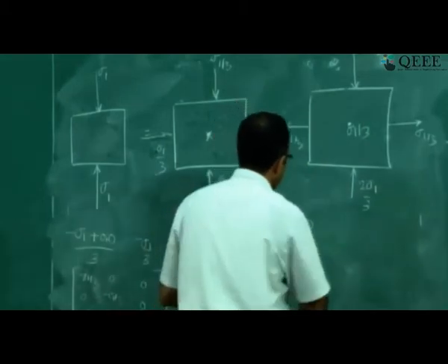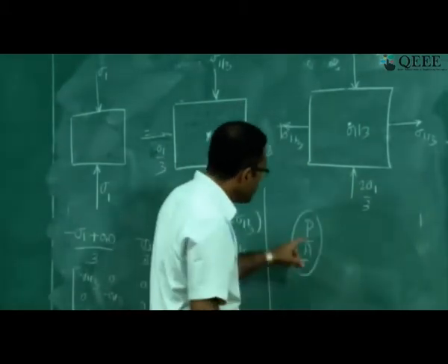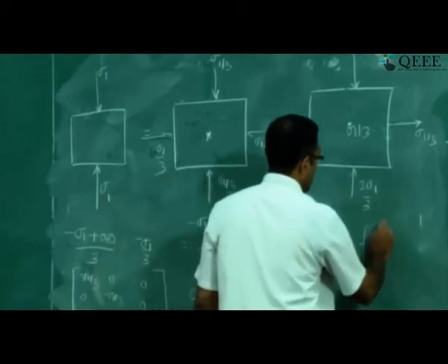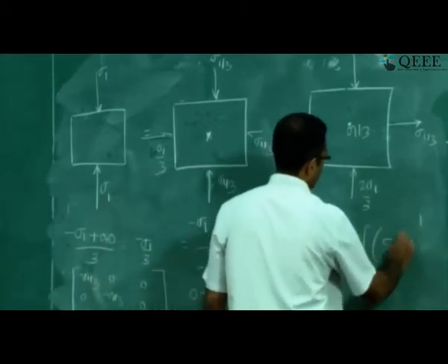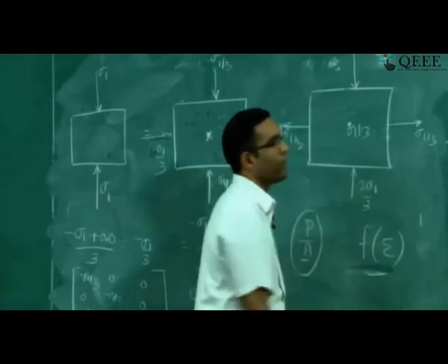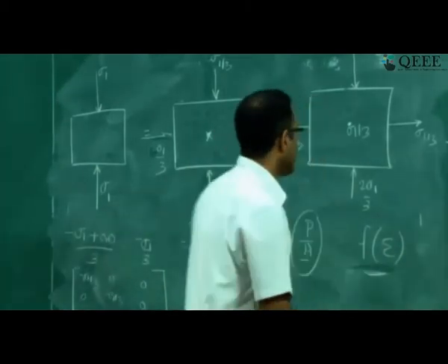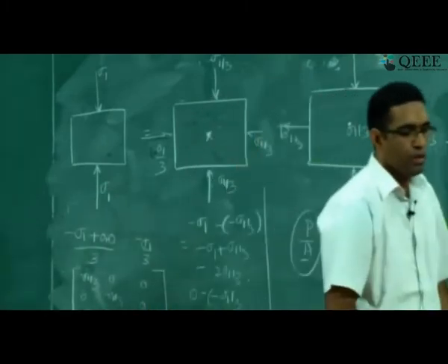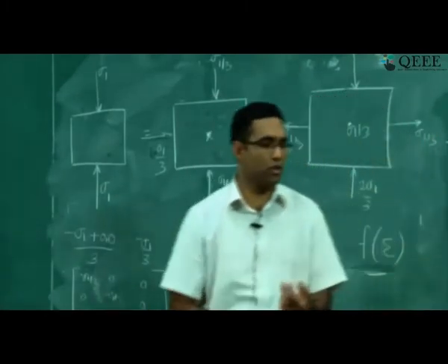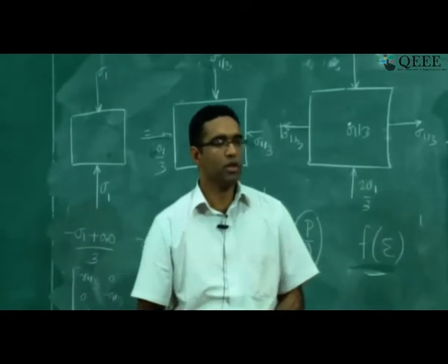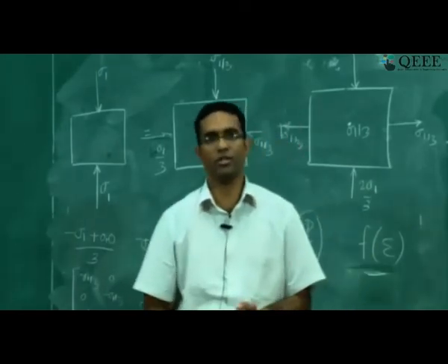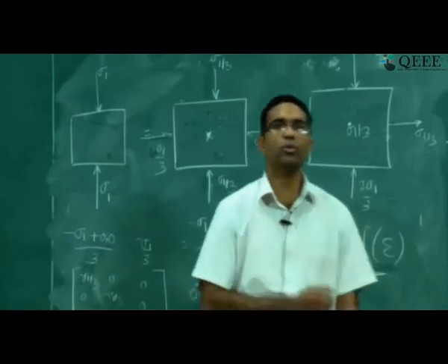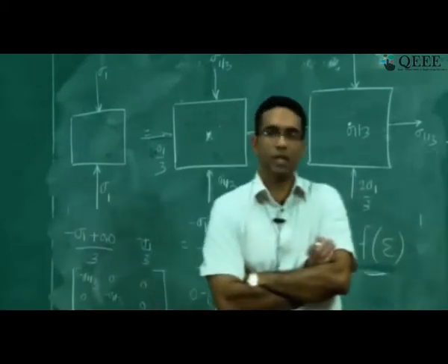There is nowhere you talk about Young's modulus when you are just talking about pure strain, right? However, when you want to relate the amount of strain induced by a certain amount of stress, you have to relate it through the material property. This function is unique for a material. So that is where your Young's modulus comes in. We also need to know Poisson's ratio, which I am sure you understand. You also know what volumetric strain means, change in volume by original volume. So with that, let's go to isotropic Hooke's law in 3D.